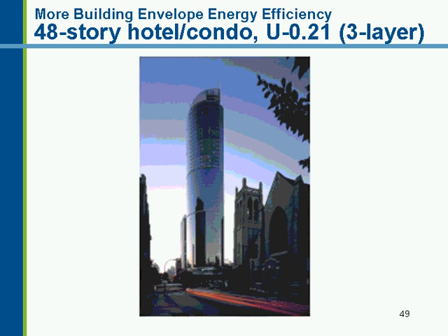And people might ask, well, U-factor, aren't these buildings usually being cooled all the time? Well, as it turns out, a lot of these buildings are in bimodal operation. So when they're occupied, which is what most people think about, yes, the people are there, the lights are on, the equipment's on, there's lots of heat, and so you're really concerned about the solar heat gain coefficient. But buildings are actually unoccupied more than they're occupied. And so in those cases, they're losing heat. So you want to make sure that they have good U-factors, good insulation to offset the heating load.